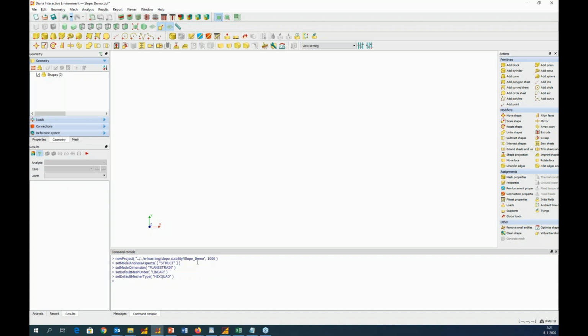Next thing now is to check our unit system. We choose SI units, so you can find the units in the bottom right corner if you click there. So today we are going to use meter, kilogram, Newton, second, Kelvin, radian. Be aware that you can change the unit at any time and it automatically updates and scales the values that you have already entered.